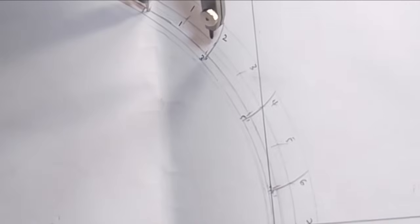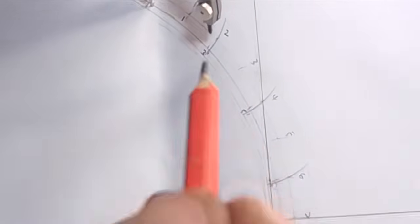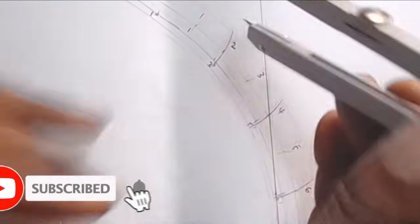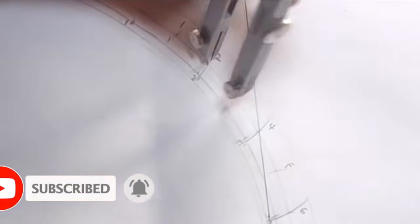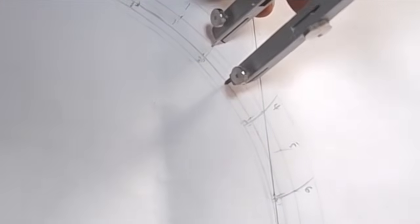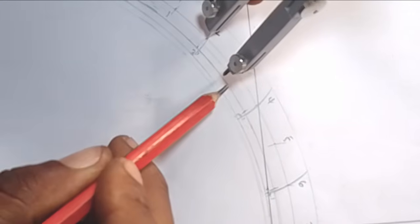Before, we doubled. But when we want to make marks on the baseline so that we can construct this arc, we have to go back to the measurement 1.6. Then stand on the even numbers, rotate your pencil like this, and make marks again on the base line. This is our base line. So make a mark. That will be 1.